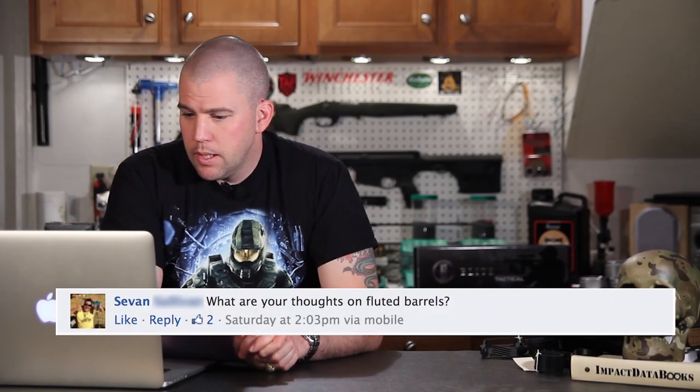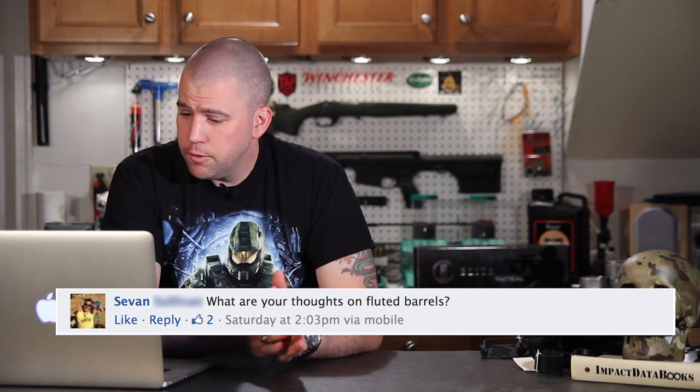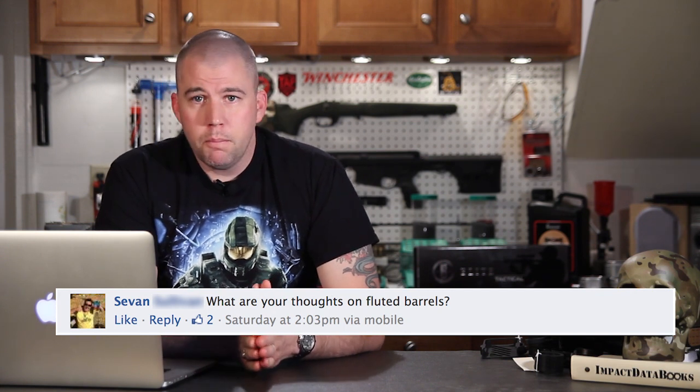Savan asks, what are your thoughts on fluted barrels? Fluted barrels really serve one main purpose, and that is to reduce weight on a rifle system. There's a lot of confusion out there on fluted barrels with people believing that they are more rigid. Well, that's just really incorrect.